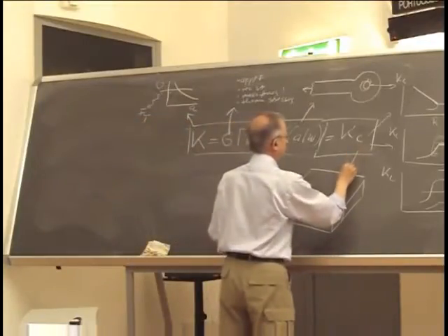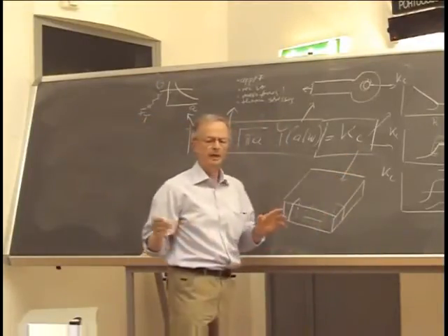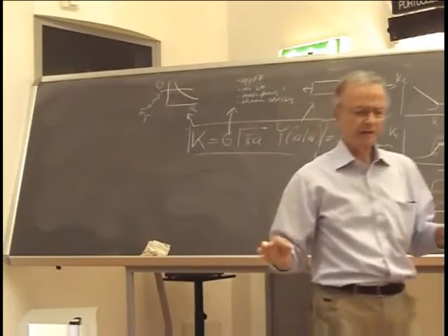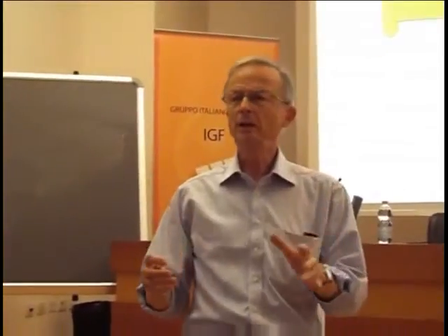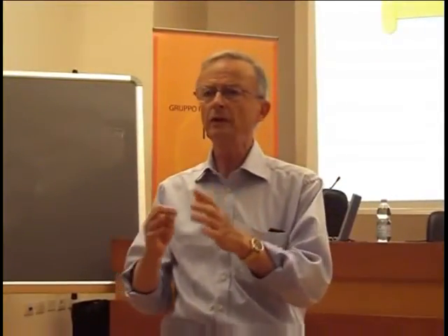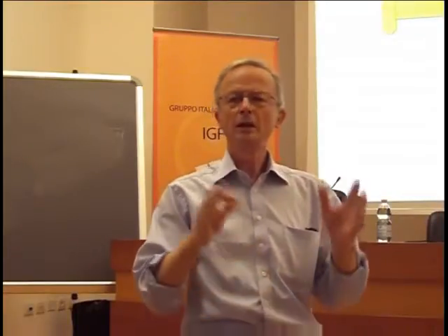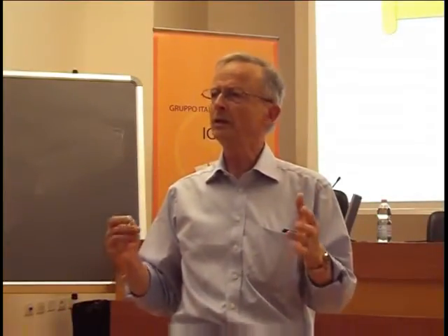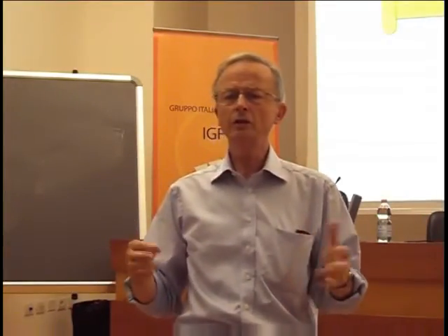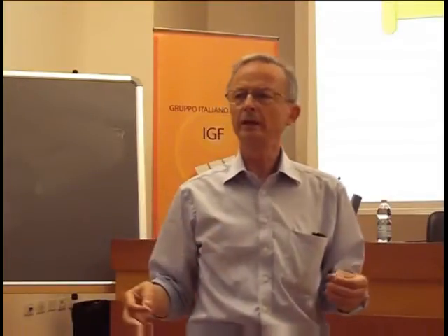Okay, something similar, I'm not giving you a drawing, something similar happens to cast and forged materials. Within one piece you can have different thicknesses, and the different thicknesses have different toughness values, you have different orientations, so it is a nightmare, you know. And you can't just characterize the material and say this is a critical K or J value of steel XYZ.